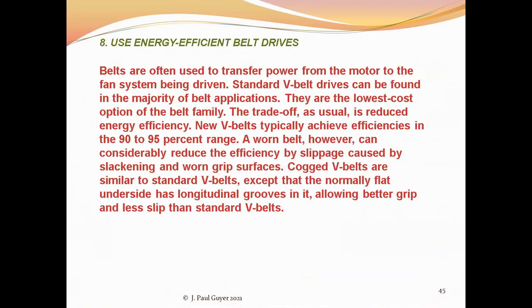High efficiency belts have been developed in recent years and are on the market, and can result in substantial improvements in efficiency of the transfer of the power from the motor to the fan over the efficiency achieved with the older typical V belt.